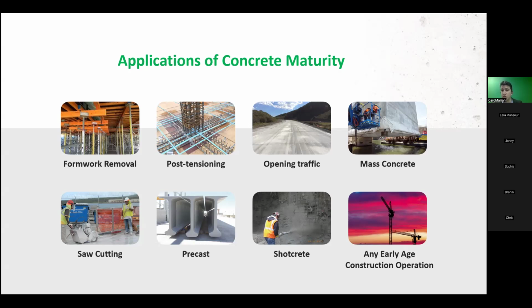Precast, even shotcrete. To be honest, we used the sensors at the Roundout project in New York. Over 1,000 sensors were used for shotcrete only. So I know it depends on the nozzle person, but as long as the sensors are properly installed, you can actually measure the strength of your element in shotcrete as well.